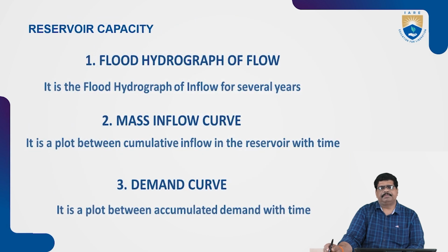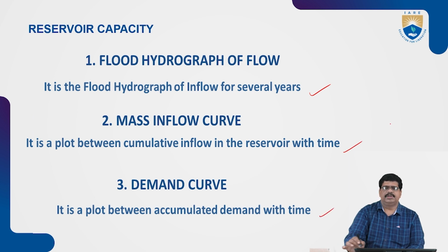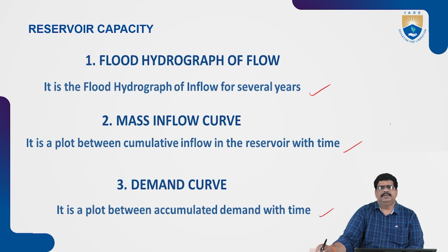Next, reservoir capacity, very important. In this, we have to collect the flood hydrograph of the flow over several years. Second one is the mass inflow curve, the plot between the inflow into the reservoir and time. And the demand curve is the plot between the accumulated demand and time. Based on these three points, we estimate the reservoir capacity.